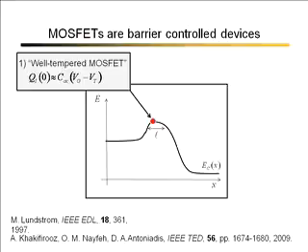Then you've got a significant amount of charge in the channel, and charge is always capacitance times voltage. But you don't have any significant charge in the channel until you turn the device on by exceeding the threshold voltage. So this is an expression of charge balance and of MOS electrostatics. The charge on the gate is balanced by the charge at the top of this barrier, which is at the beginning of the channel, and it's just the gate capacitance times the gate voltage minus the threshold voltage. This is MOS electrostatics. This is the Poisson equation.